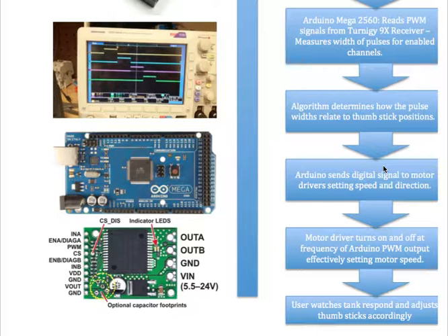With pulse width modulation, we can say we want a duty cycle of 50%. That means it'll be in the on state for 50% of the time and the off state for 50% of the time. So if we have a 24 volt signal and it's on half the time and off half the time, what's the average voltage for the motor? Well, if your answer was 12 volts, you're right. If your answer was anything else but 12 volts, you're not right.